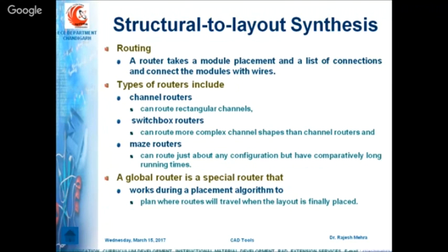Apart from these routers, we have other routers also, like global routers. Global routers are used to route your circuit globally. Means that these routers are going to travel all over your design. And examples of these routers are your global clocks, your VCC, ground, because you have to give ground and VCC to your complete design. They are part of global routing. They move in different parts of your design. And then global clock you have to provide to each and every section of your circuit. So that is also part of your global routing.